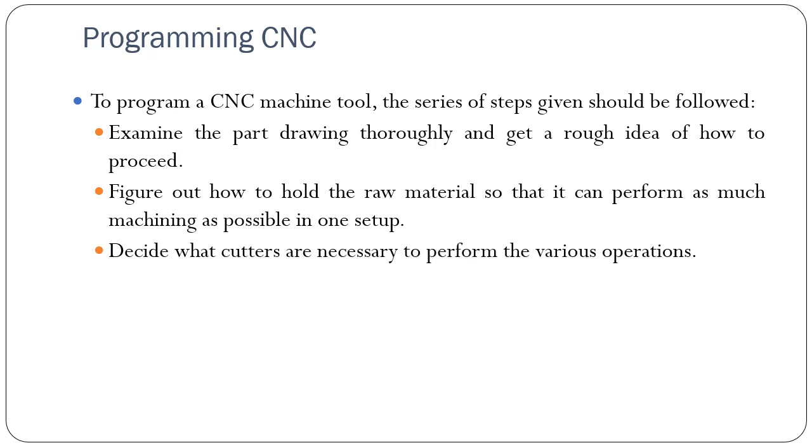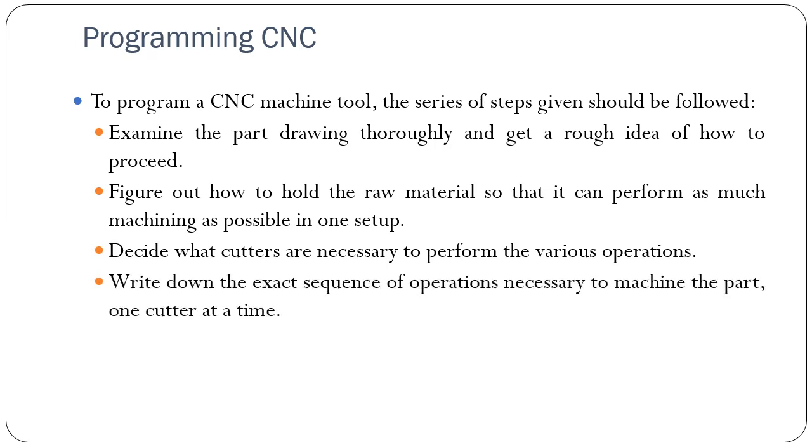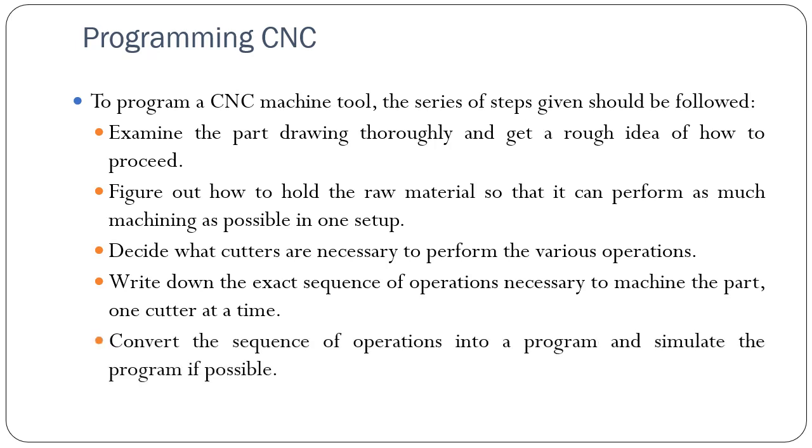Number 3. Decide what cutters are necessary to perform the various operations. Number 4. Write down the exact sequence of operations necessary to machine the part, one cutter at a time. Number 5. Convert the sequence of operations into a program, and simulate the program if possible.